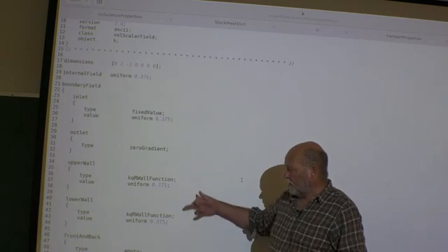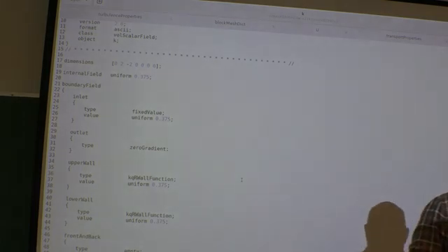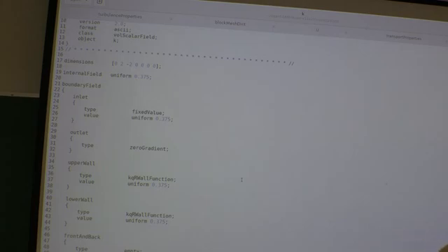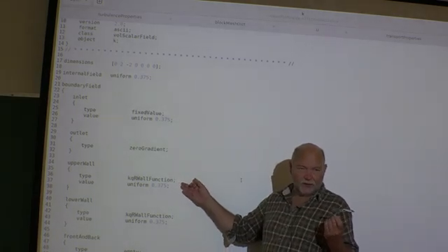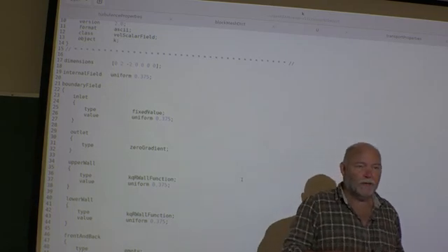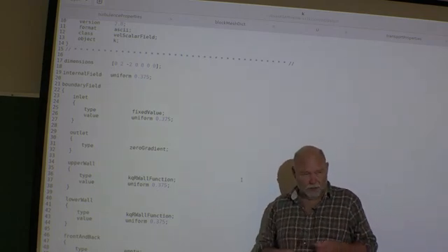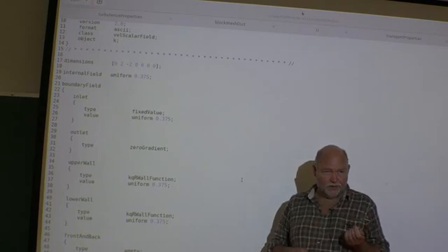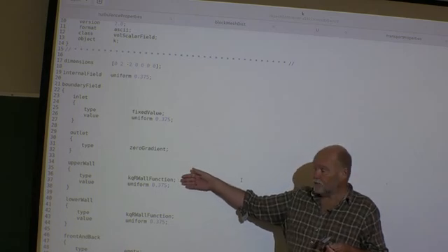They use a wall function. This is something we discussed last time. That's important. When should you use a wall function? You should use a wall function if the distance to the center of the nearest cell close to the wall, the y plus distance there, is bigger than 30. Then you should use wall function. Else, if it's smaller than 6, then you should use normal boundary conditions here.